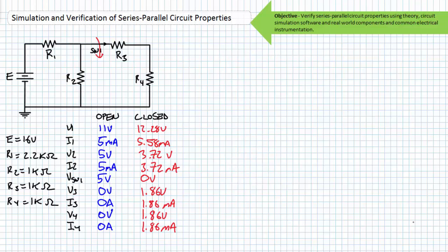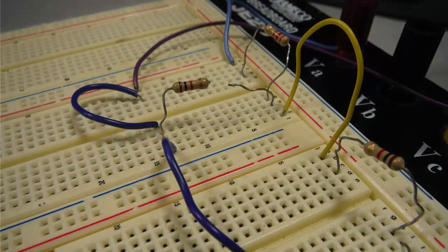Far more expedient than your comparison of all these observations with that of expected values is your spatial awareness and basic powers of observation. Look at the circuit. Opens are often visually identifiable with a burned open component or a severed or misplaced wire, or in this case, a lead that's been flexed one too many times and is simply snapped off.